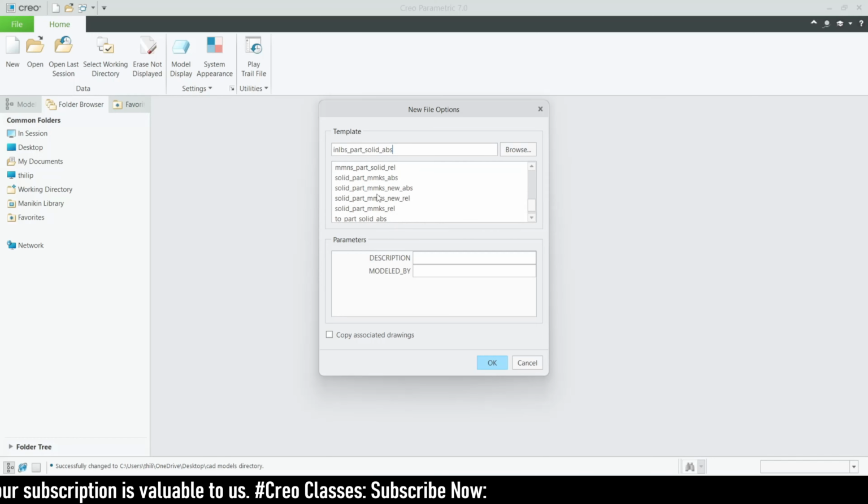If you need to add any description for this part, you can also add it here. Modeled by is nothing but the author name, like who created this drawing. I'm going to enter our channel name as the model name, and then you can directly click on OK. After clicking OK, this is our interface inside part modeling.